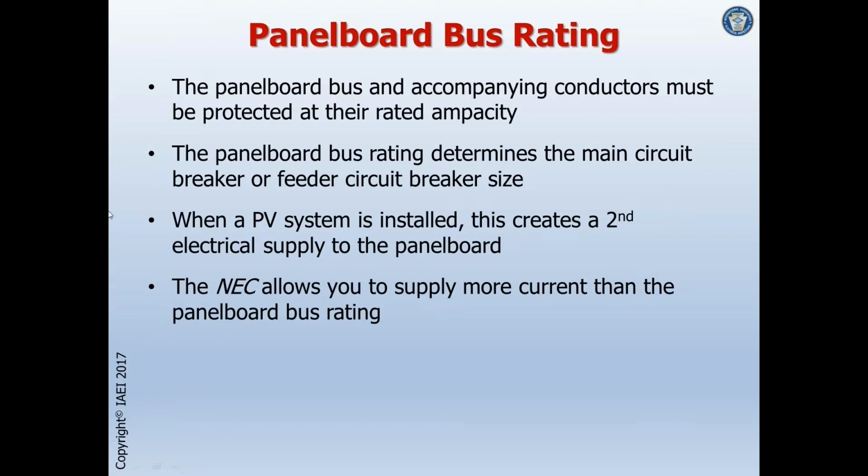Well, what's unique about PV systems is, again, they're not a load, they're supply. So when we interconnect a PV system or an inverter to a panel board, that's a second electrical supply to the panel board. It's like adding another main breaker. Some people think, well, if my PV is supplying current, then that means the utility's not, so why does it matter? Well, don't think about who's supplying it, just think about, can I increase a supply to greater than the ampacity of bus bars? And the general answer is no, you can't.